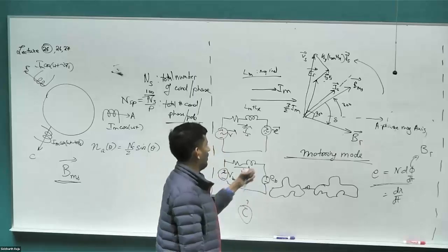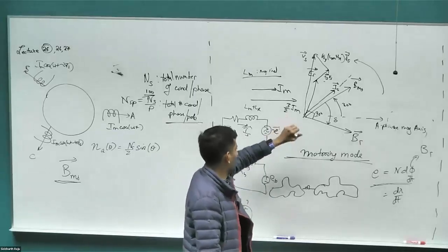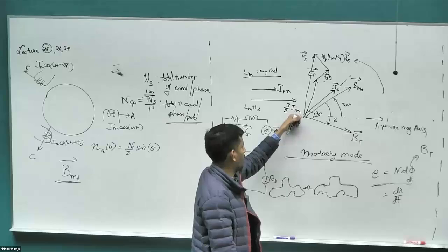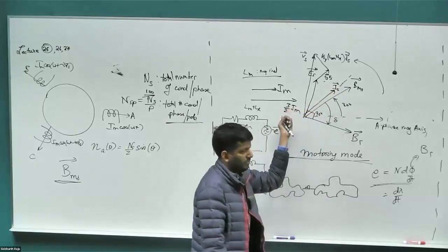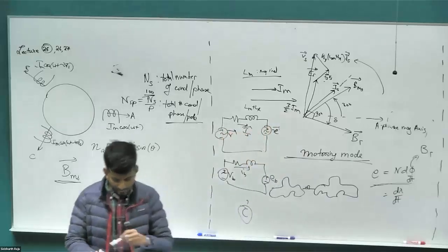Right? So if you want to take your space vector and convert it to phasor, take a screenshot at one particular time, which is exactly what I've drawn here. Scale all of these space vectors by a factor of 2 by 3 to take out this value, and then you have your phasor representation. Right? Do you have any questions?